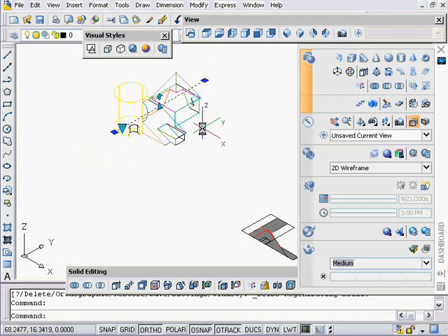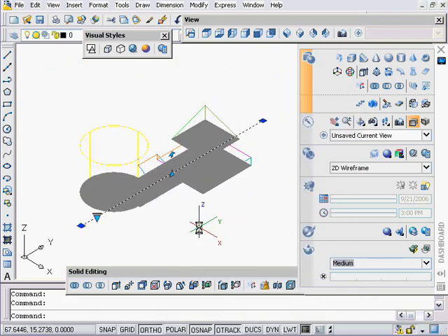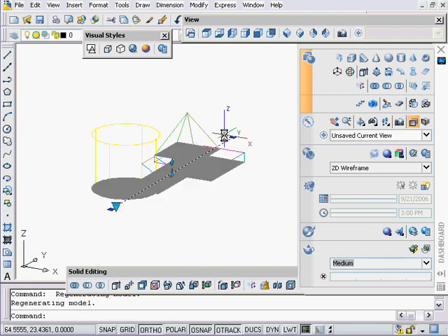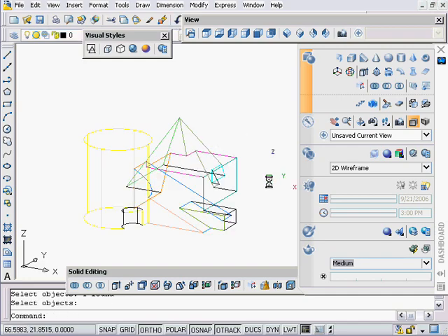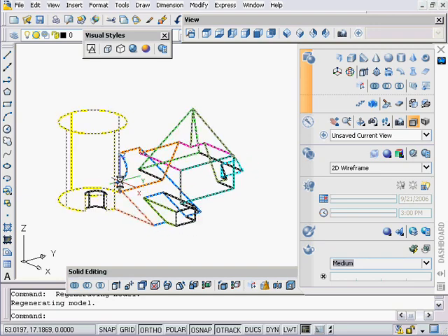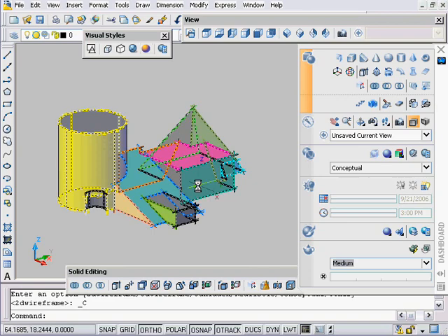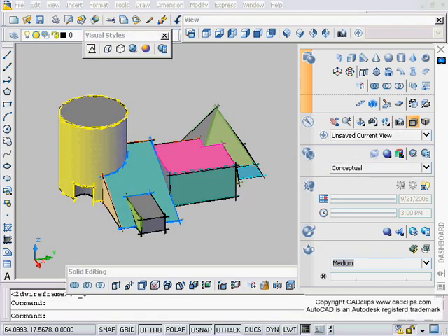Move that back. Over to there, go to our 3D view. Click on here, right click. Enable that live section as you please. So they can be placed in plan, in elevation, in section, in a 3D view. All your settings, right click on it, have a look at the options, right click everything every time, wherever you get a chance to, and then use your grips as well to manage your section planes.